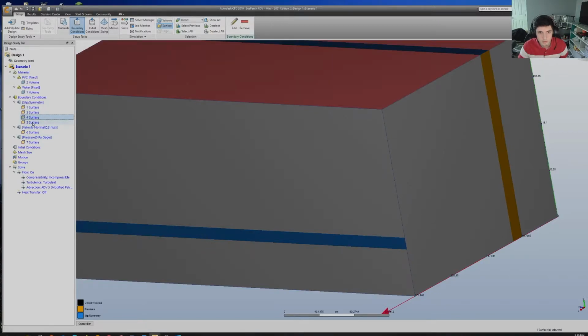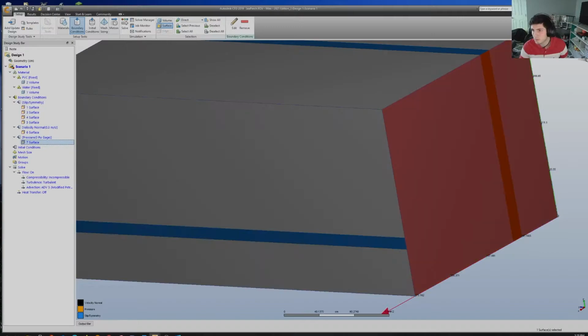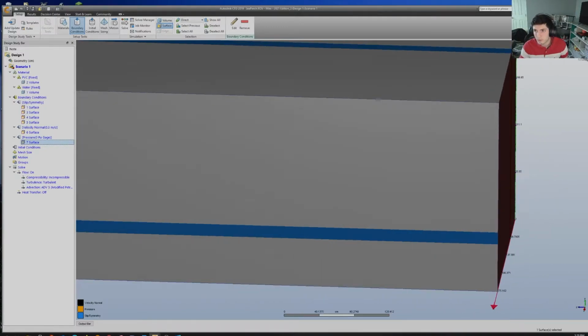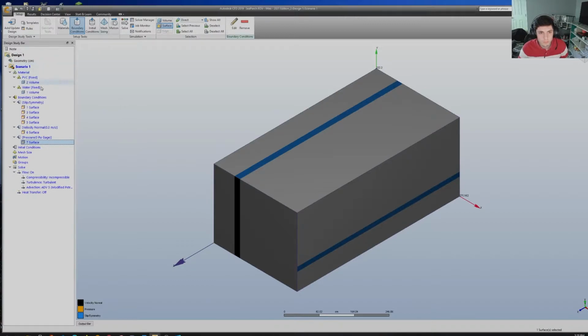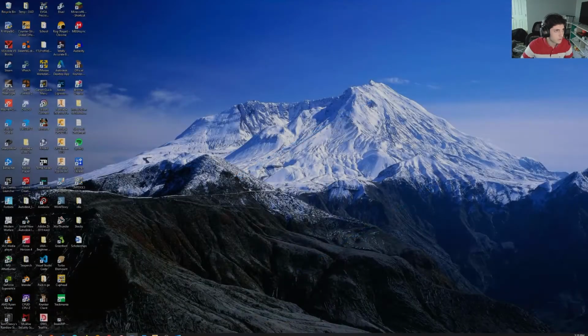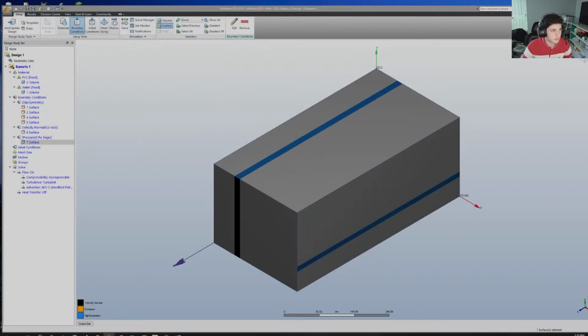Okay, so we have all the surfaces defined because there are 6 sides of a cube. Okay, so then we are good. Now, if you mesh this in the normal way, you would have to right-click on mesh and click auto size. There are tutorials for that you can find pretty easily. But because of this method, we're only testing the hydrodynamics of the water around the body, so we're not going to need to do that more complicated mesh.